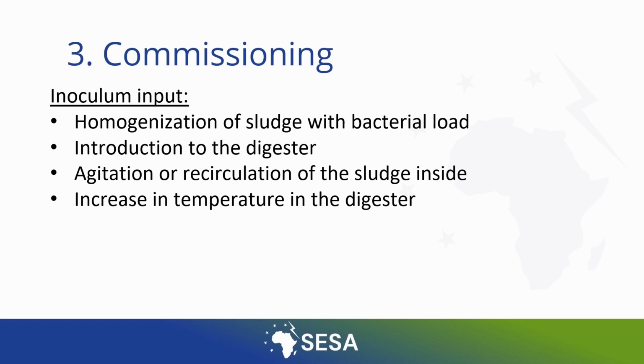Ideally, if you do not have an acclimatized sludge from another biogas plant, animal sludge can be introduced to the reactor, and water if necessary. This will provide a higher amount of bacteria, but commissioning will be slower than if digestate from an operating biogas plant is introduced.